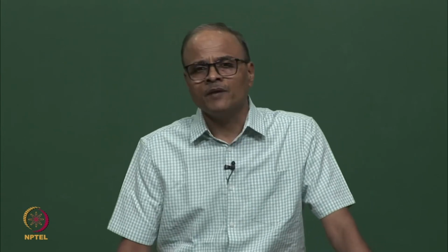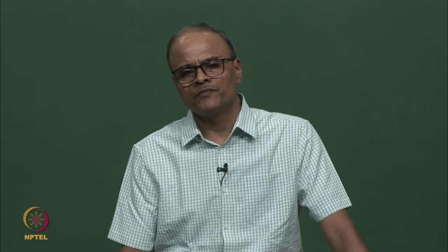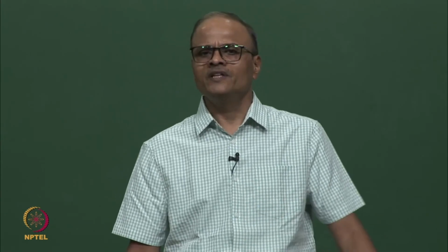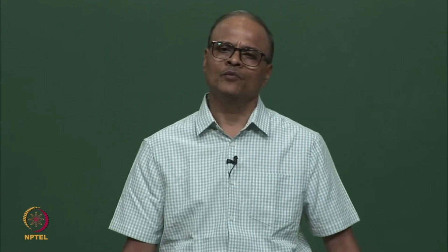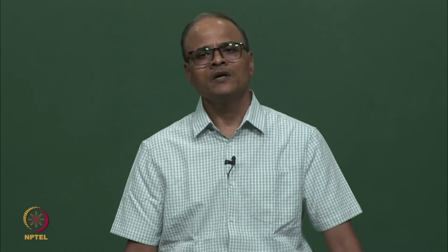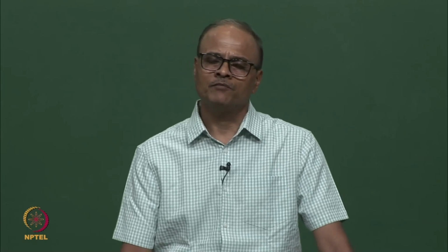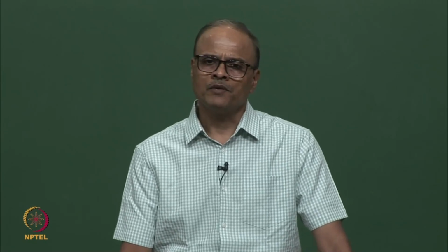Hello everyone, welcome to this lecture. In the last few lectures we studied FRF measurement using an impact hammer and a shaker. Once the FRFs have been measured, the next step is to find modal parameters from them. How is this done? This is done by curve fitting of the measured FRFs or IRFs. In this and the next few lectures we are going to study modal parameter estimation methods, which are nothing but curve fitting methods. In this particular lecture we are going to study modal parameter estimation using the peak picking method, which is probably the simplest and most straightforward approach to modal parameter estimation.